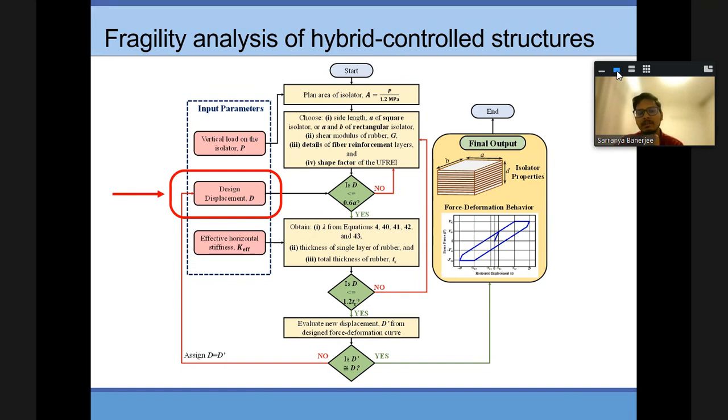No, Sensei, I want to maybe use the time history analysis, but then to define the trilinear curve or to define the force displacement behavior of the isolator, I don't know if I can use this model. Maybe instead of the trilinear model, I am thinking of using the equivalent linear model for time history analysis.